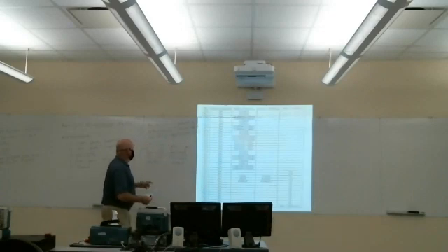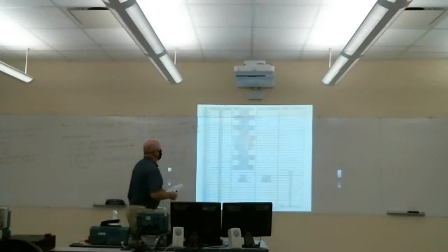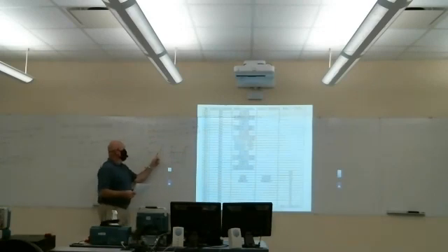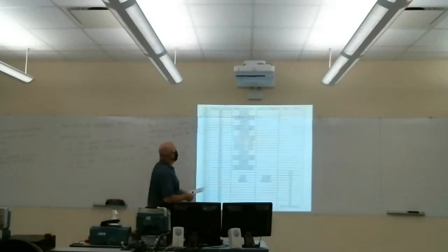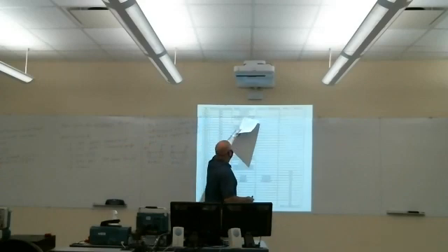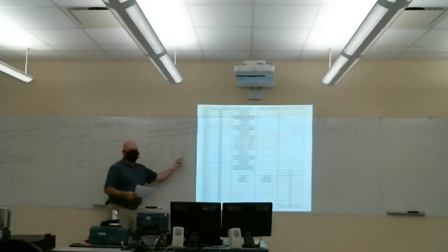for P1.2, we have to set the port 1 selection 0 and selection 1 registers. We have to set 2 bits in that for P1.2 to have it general purpose I/O. We need to make sure that the second bit, so this is 0, 1, 2, is 0 here and 0 here. If we want to have it the serial receive function, we need to make sure that we've got a 0 in bit 2 here and a 1 in bit 2 in this particular register. Okay, does that make sense?